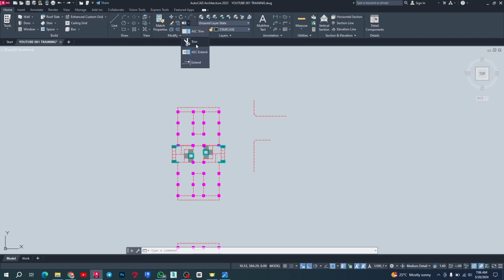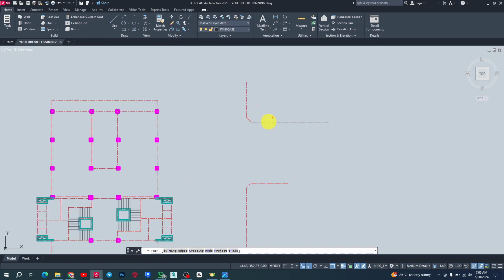And then you have extend, trim, and that. So you have extend. You want to extend this line. This is trim right now, so you can trim this line. Let's say I want to extend this line, but the current command I have is trim. You can just hold down shift and you activate it as extend, right? So you extend at that point, and you can delete and things like that. You can trim, right? You can trim it. So lines, you want to draw circles. So these are just some basic things.